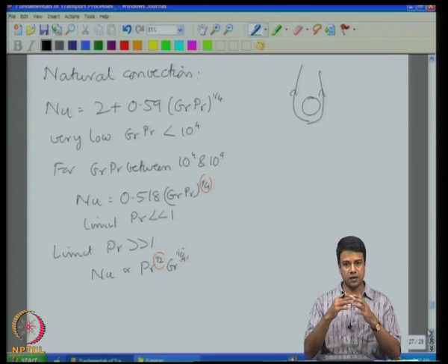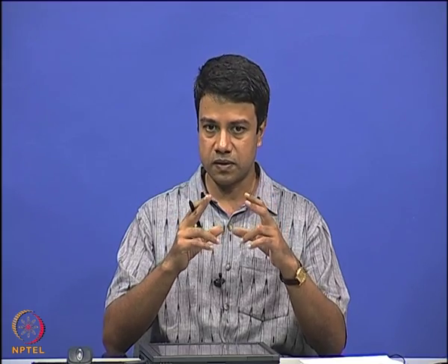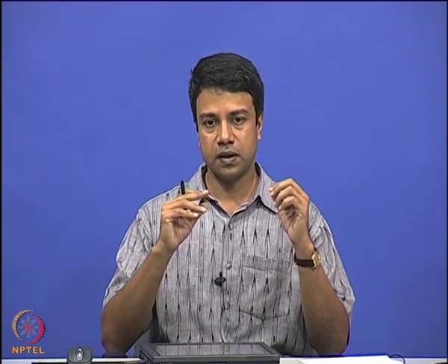these different forces, we actually try to solve for the entire problem around the object. It is difficult to solve for the entire problem, but can we make approximations in regions where we expect either convection or diffusion to be dominant? If the Reynolds number is small, momentum diffusion is large compared to momentum convection. Viscosity is large compared to inertia. You can neglect inertia and solve for the problem by just balancing the viscous forces.